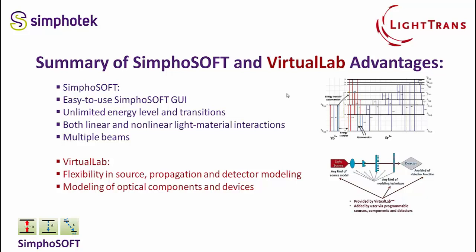So now I have finished the 3 examples, and I'll go back to the PowerPoint presentation. First, I'll summarize SimphoSOFT and VirtualLab advantages. With SimphoSOFT, you have an easy-to-use graphical user interface where you can set up a very complex energy level diagram with an unlimited number of energy levels and unlimited number of transitions. SimphoSOFT allows both linear and nonlinear light material interactions, such as 2-photon absorption, energy transfer, and so on. And you allow multiple beams, 2 or more beams, which can be used for amplifiers or other applications.